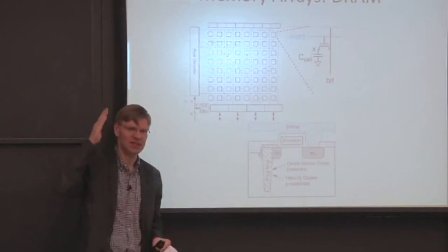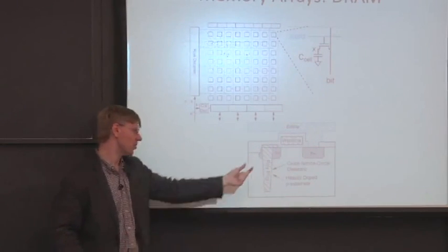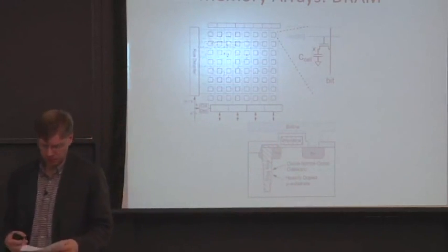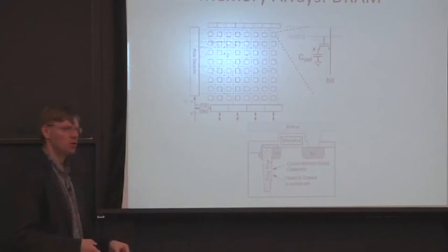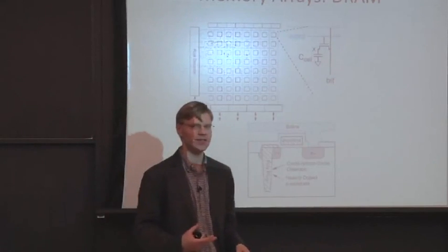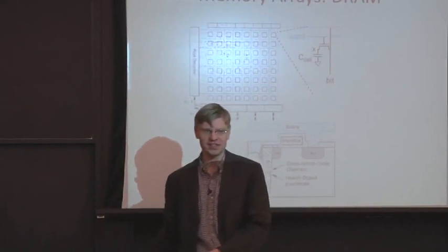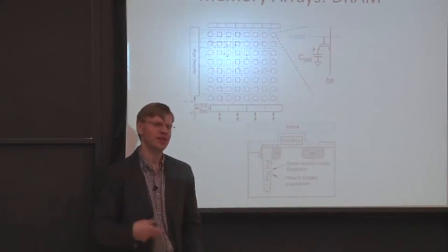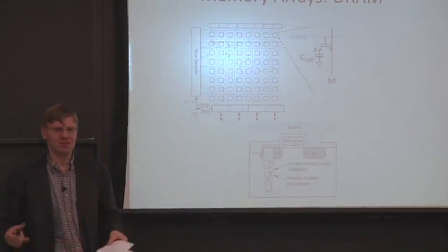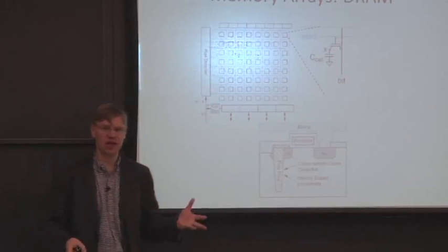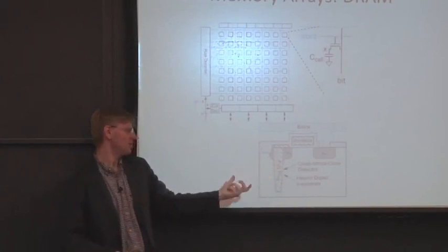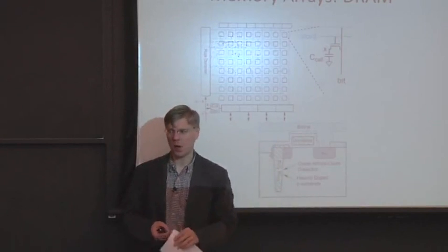And the reason we do this is because we want to see that the actual capacitor is very long, very deep into this. And one thing I wanted to point out is this is typically really hard to go build on your standard CMOS process. So this is hard to go build on something like a logic process. You have to go build this, let's say, in a special DRAM-only manufacturing process. So it's sometimes hard to mix that. There are some technologies which allow you to mix them, but when you do that, people haven't really designed ways to make the DRAM cells as small.